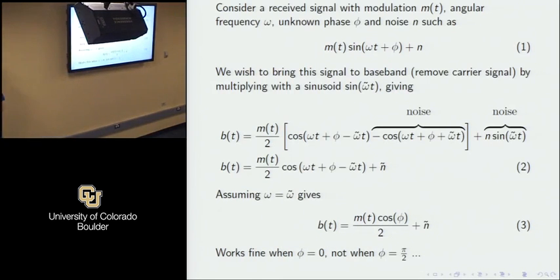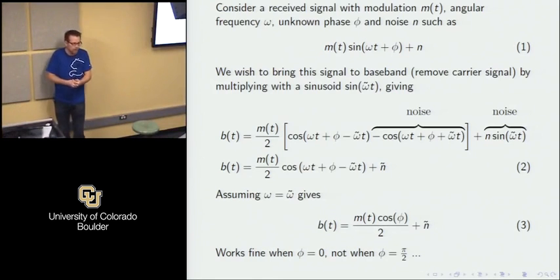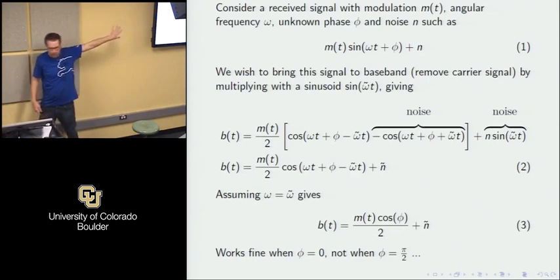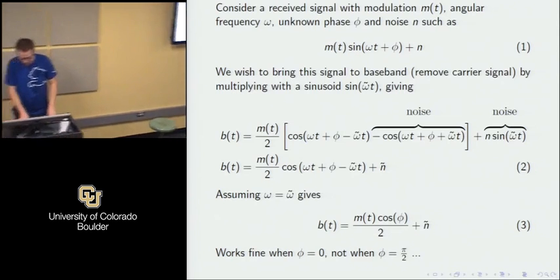That is, if we look at one of the data sets, the 16 megahertz one, we end up with an IF of like 4 megahertz. So even if we're off a little bit in our oscillator in the front end, we're still going to end up roughly 4 megahertz off. But if we want to bring it down to baseband, just one sinusoid just doesn't cut it.